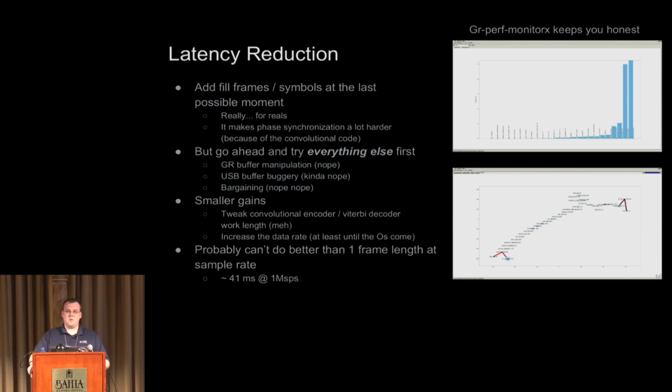I've done stuff like this before, but ultimately what happens is if you try to add fill frames or fill bytes early in your flow graph and you have several buffers down, GNU Radio is going to fill up those buffers all the way from the sink. So you're going to have all this latency, because it's trying to feed your sink, which is your UHD block.